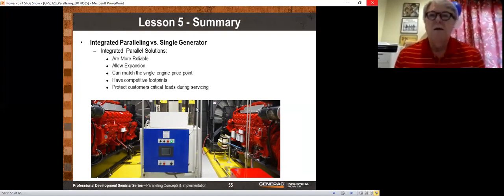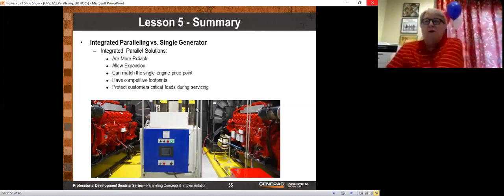Yeah, that design is very common. In fact, a lot of times when you have small facilities and small generators, it probably doesn't make sense to go the paralleling route. The smallest natural gas generator that we make as standard to parallel is 100 kilowatts. The smallest diesel generator is 300 kilowatts. And we can make generators smaller than 300, but a 200 kilowatt generator in parallel is about the same price as a 300. So if you have smaller generators, then you may choose to go that route